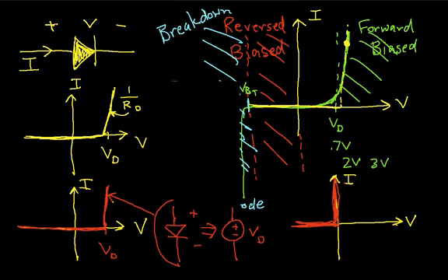And so in this case, when the diode is forward biased, that is when the voltage is such that you have the diode conducting current, then your diode is just representing a short circuit because the voltage is always zero and you can run any amount of current through it that you want to. And when the diode is reversed biased, out in this region, your diode is modeled by an open circuit because no matter what the negative voltage is out here, the current is always zero.